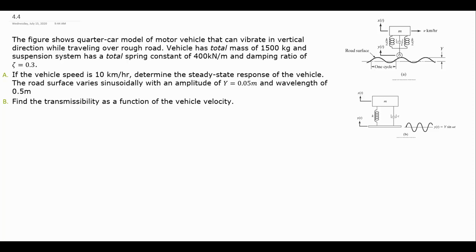So we're going to have peaks and valleys that are going to be regular. And we're going to assume that the wavelength, or the spacing between the peaks, is going to be constant. So what we want to look at is what's the response of the car as we go over this washboard road. The washboard road is going to act as a prescribed displacement on the bottom of the tires, and then that displacement is going to be transferred up to the cabin of the car.